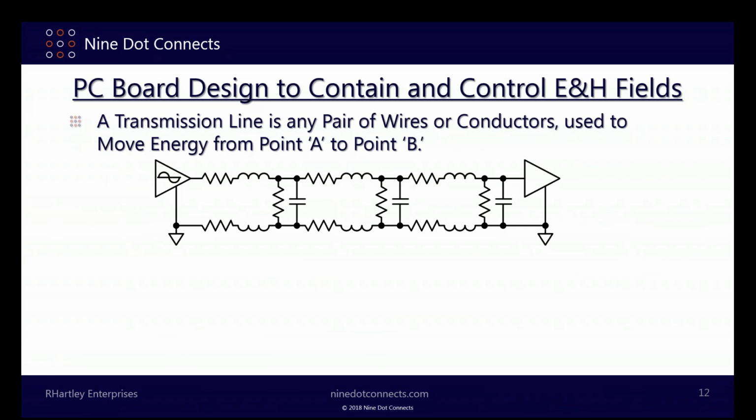If the IC on the left is point A, it's the driver driving this transmission line. As you can see, the copper features and the dielectric between them are made up of elements, and they show these elements in a transmission line as the resistor is the resistance of the copper. The inductor on both sides effectively is the inductance of the transmission line, based partially on trace size, but based mostly on spacing between them. The resistor going line to line is an attempt to show, when you're doing a transmission line model, that the dielectric material itself is not perfect. It has some loss associated with it.